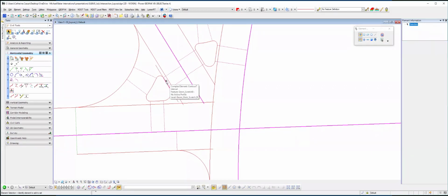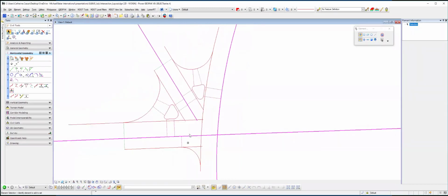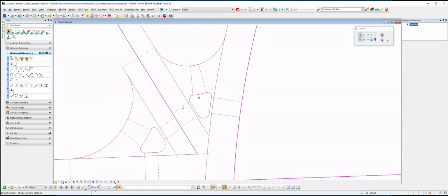They come out and they hit that end of radius on each one. Actually, they're connected to the tangent, not the radius itself. In case I have to change or move the radius, then it will impact the tangent, and then these lines will adjust accordingly. So these are great. You'll notice I have them at all the radius points in order to be able to lock that in. If I need to do any type of pavement warping, that becomes critical.